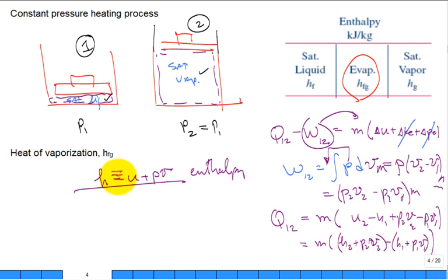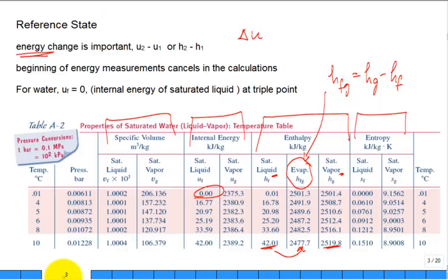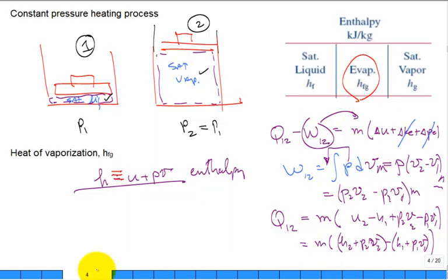That new property is conveniently tabulated. You can go back and check, grab some random numbers in the textbook and see. Let's go back here. Let's just say, is h_f right here, is that 20.9? Is that equal to the internal energy, u_f, plus the pressure times the specific volume? Chase your units, it will be precisely the same. So why did they just repeat numbers in the textbook? Well, because this is a convenient property to have known as the enthalpy.